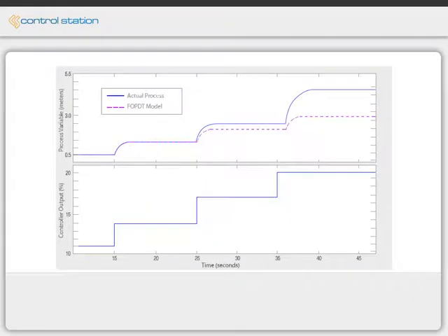As discussed earlier, a critical step in controller design and tuning is the fitting of the linear FOPDT model to dynamic process data. It may come as a surprise to learn, then, that no real process has its dynamics exactly described by this model form. A linear FOPDT model is just too simple to describe the higher order, time-varying, and nonlinear behaviors of the real world. Shown on your screen is the plot of the exact same gravity drain tank process from earlier, along with the approximated response of a linear FOPDT model.